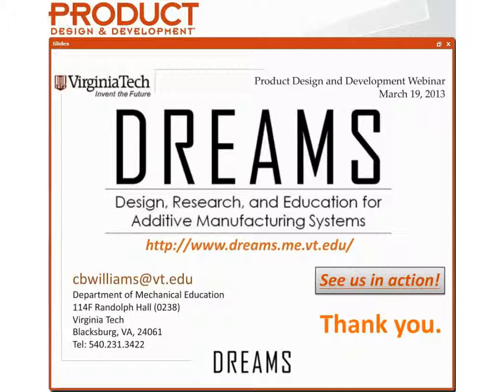No, yeah, we've done surface finish and the measurements as well. They're sort of in the 0.3 Ra, like 0.3 micron for glossy without any kind of polishing. Obviously, with polishing, it goes a lot lower. As far as metals go, we typically say it's sort of like a sand cast. It does start with a loose packed powder, so it does have a powder-like surface finish at the end. Those tend to require machining and finishing afterwards for the metal parts.